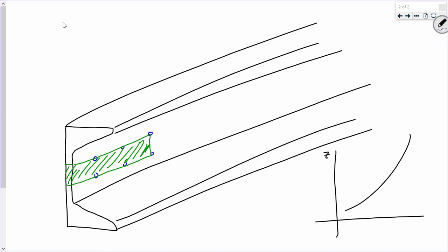But what we say is that if you're under 15 feet, we say no, no, no. We're going to have just a constant value. So KZ, if your story is 15 feet or under, use that constant value. Anything above, use that other one. So there's one that says Z over ZG and one that says 15 over ZG, right? That's the one you'd go with if it's under 15. Does that make sense? And any of the other associated parameters, like the ZG and all that, I'll probably give you to make sure that you have them. Did I answer your question?